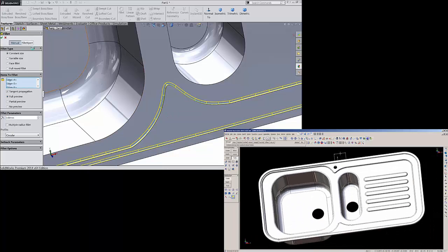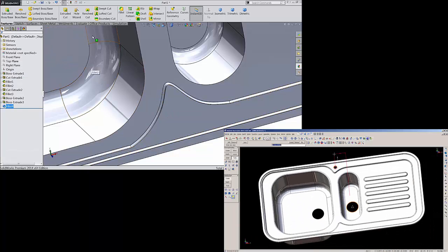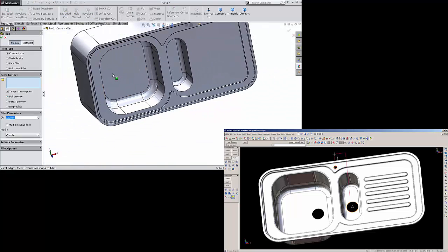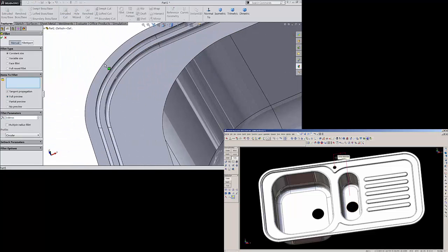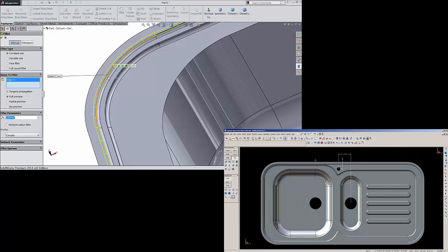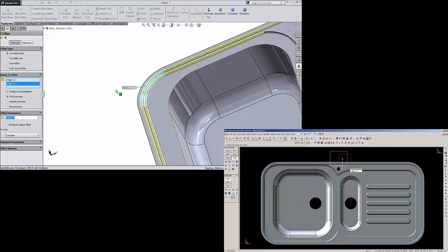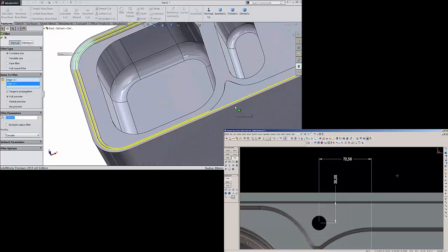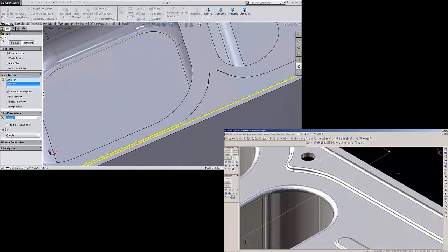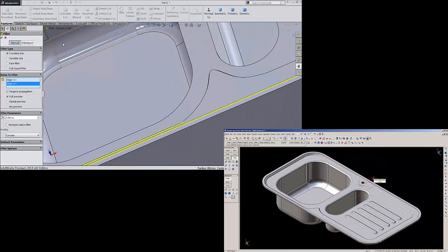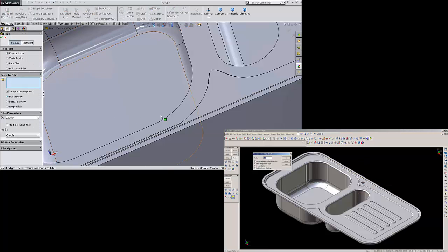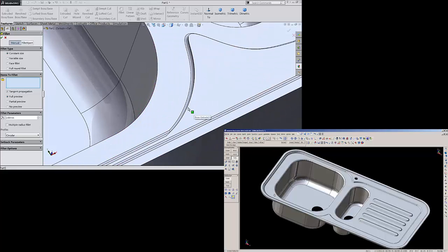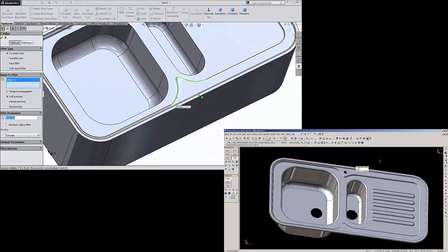Okay. Now again keep fillet, this time choose top surface and this also top surface, select OK. Fillet, keep 2 mm and here select this face.